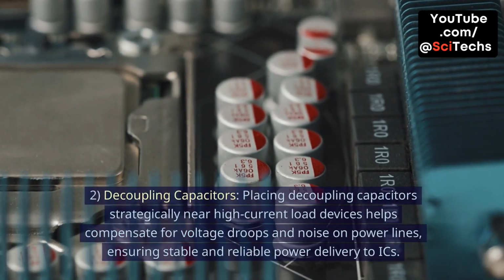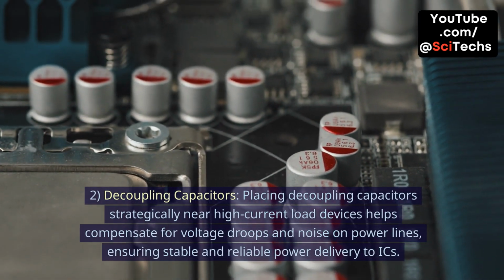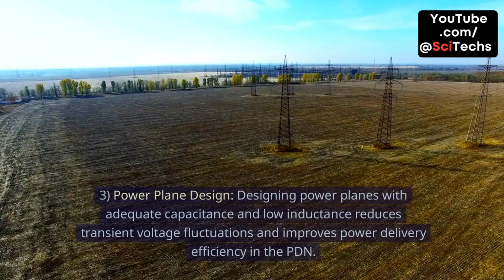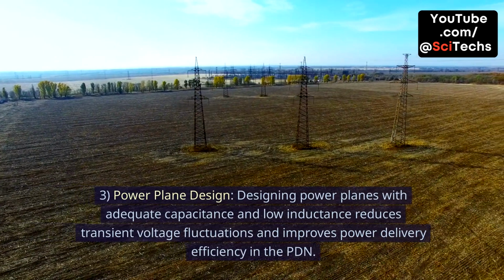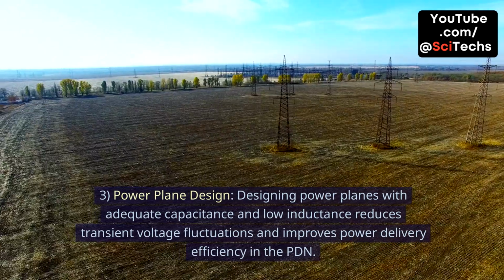2. Decoupling capacitors. Placing decoupling capacitors strategically near high-current load devices helps compensate for voltage droops and noise on power lines, ensuring stable and reliable power delivery to ICs. 3. Power plane design. Designing power planes with adequate capacitance and low inductance reduces transient voltage fluctuations and improves power delivery efficiency in the PDN.